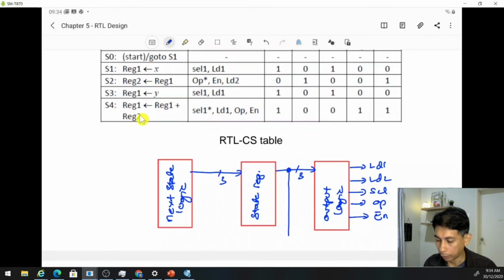And again, we use Moore FSM, so you need to have feedback from this to this, and we will use the negative edge triggered clock. All right, and of course you need to have the reset. This is the clock. And do we have any input to the controller or finite state machine?